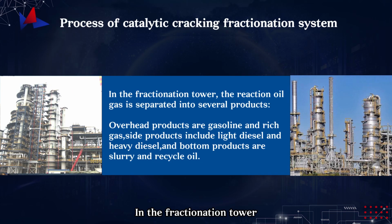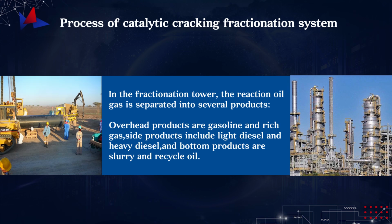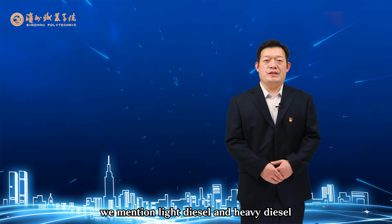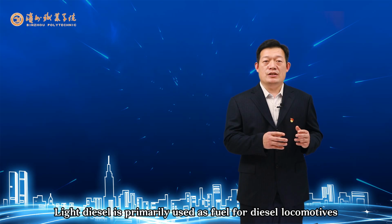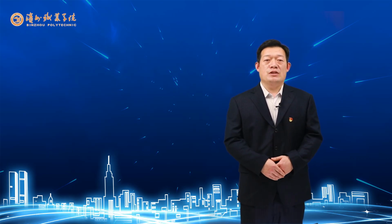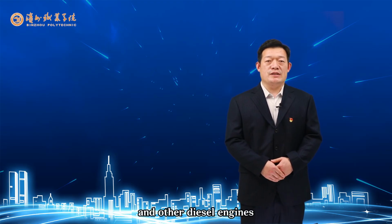In the fractionation tower, the reaction oil gas is separated into several products. Overhead products: gasoline and rich gas. Side streams: light diesel and heavy diesel. Bottom products: slurry and recycle oil. Here, we mention light diesel and heavy diesel. To expand slightly, light diesel is primarily used as fuel for diesel locomotives, tractors, and various high-speed diesel engines. Heavy diesel is mainly used as fuel for ships, power generation, and other diesel engines.